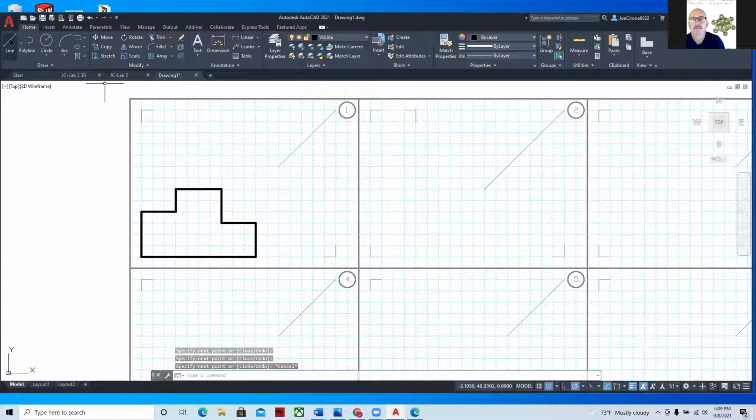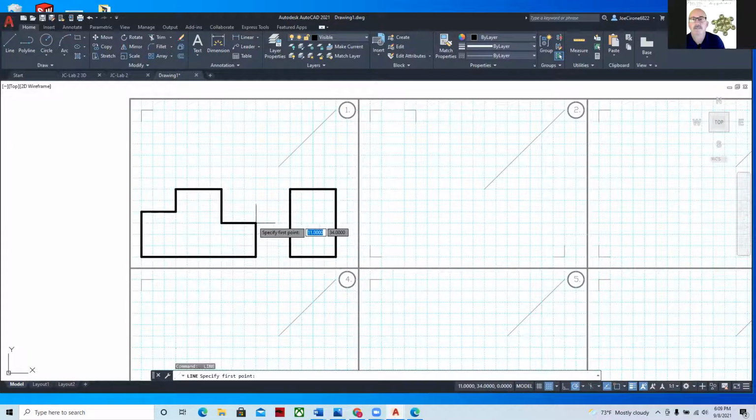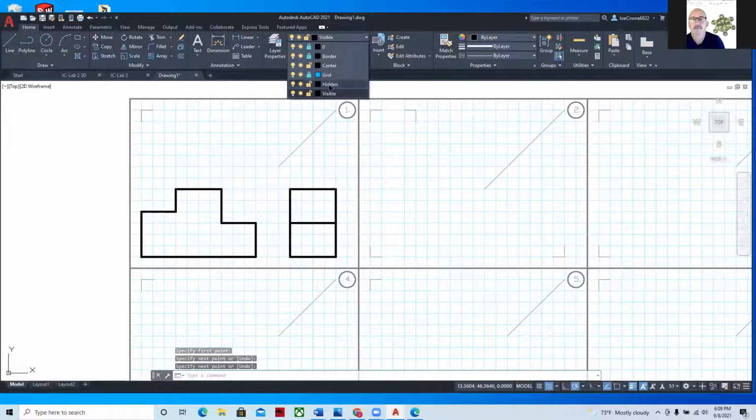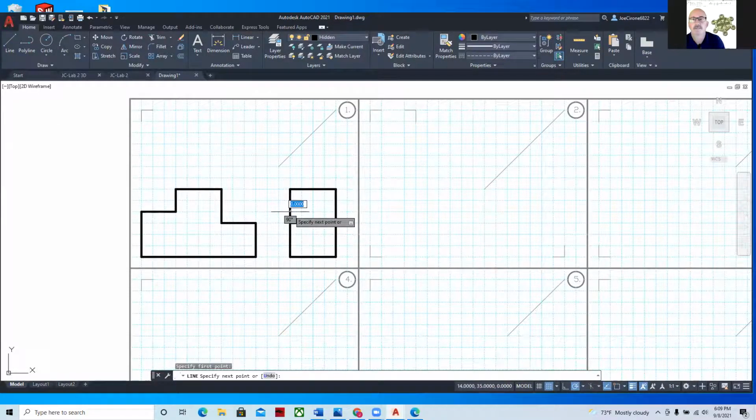and then we'd create the right side view of it. And the right side view would be lined up with the front view. And so we would come over 4 units, and then we would come down, over and up. And then we would project this line over here like that. And then we would use a hidden line to project over this line here. And then we would draw the top view in the same fashion.